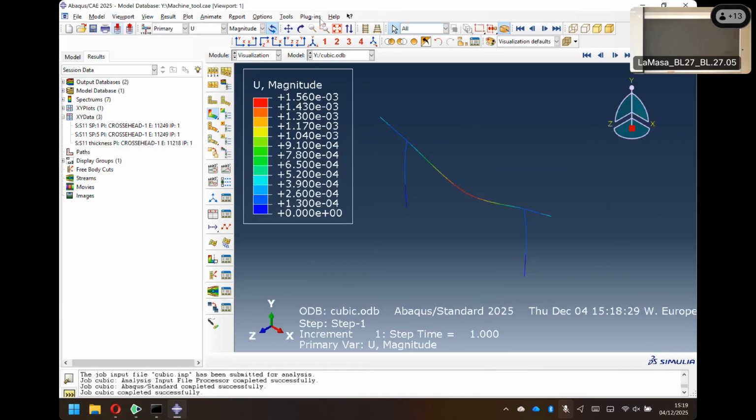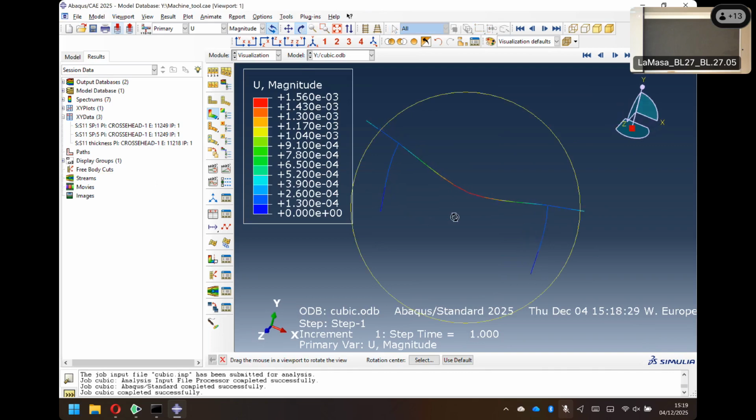You see now that this was faster, it's easier to look, it's easier to model. We are modeling actual beams with beam elements. So honestly, if I have to bet, I wouldn't bet too much, but I would bet that the solution of the beam elements is more correct.